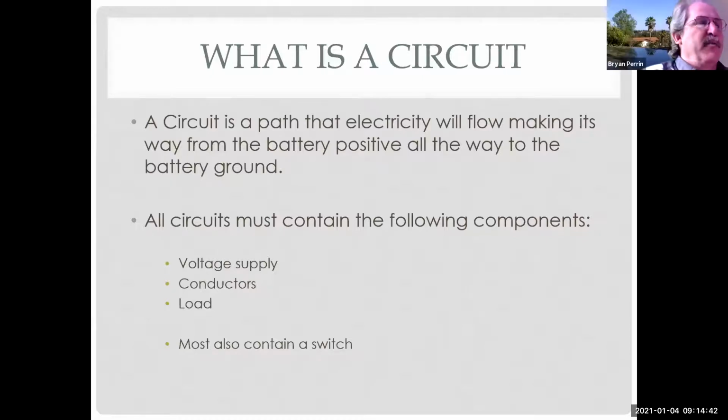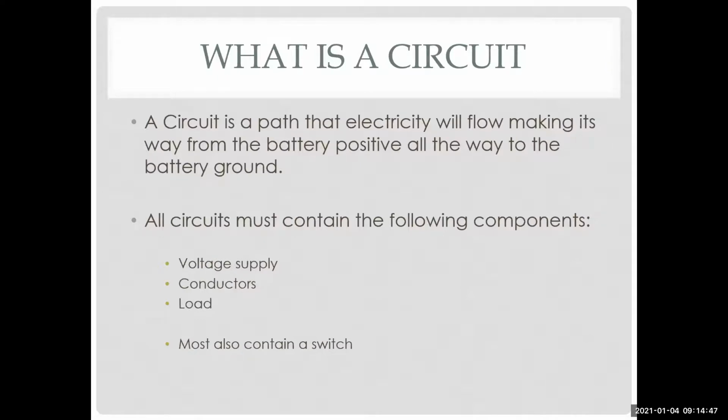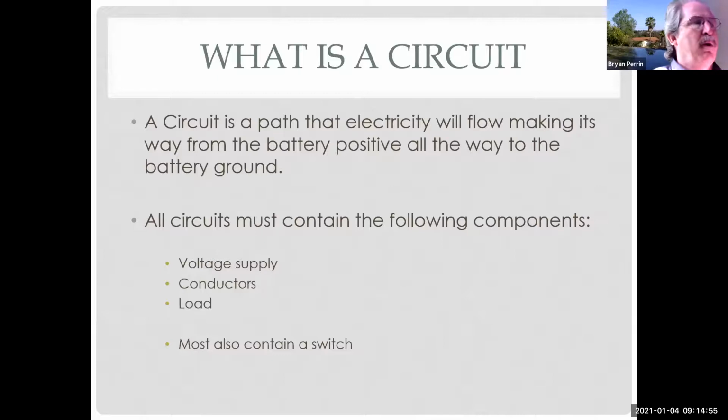It is a control device, but it's a conductor. The current has to flow. There's no voltage drop on the switch, so therefore it's a conductor. In a perfect world, there's no voltage drop. All conductors are allowed a certain amount of minute voltage drop, both through a switch or through electrical connections or through wire, because there's always some resistance, but it's very, very small.